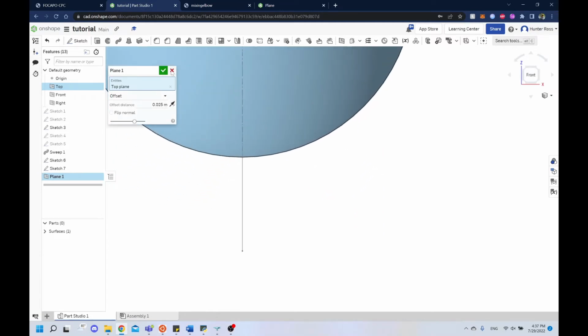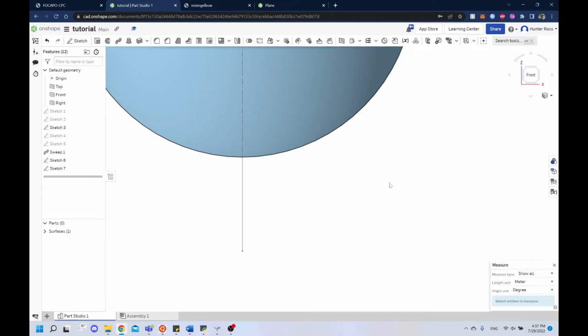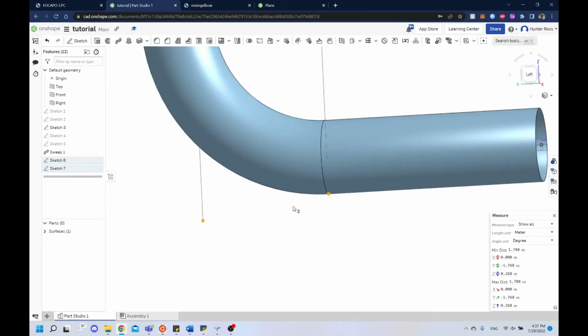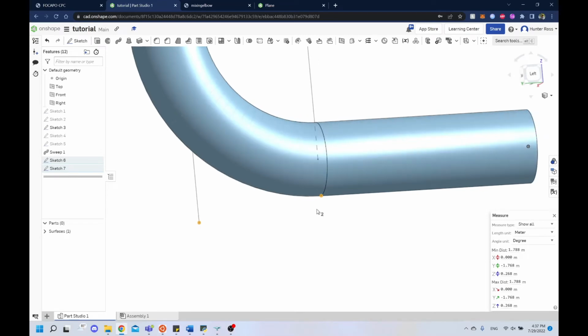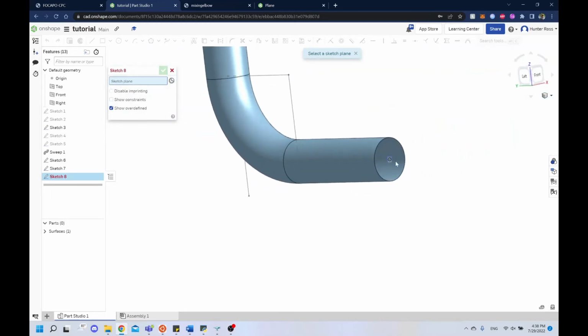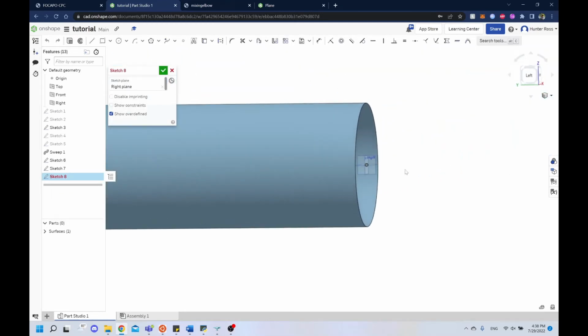How can we measure this? We can measure it by clicking this measuring tape. Click from here to here, and it'll tell us the minimum distance to get to those two. Oh, no, that's the wrong point, because it's finding the minimum distance between these 2 points. So you could do some geometry and figure out the distance here, but let's save some time. Let's just make another line.